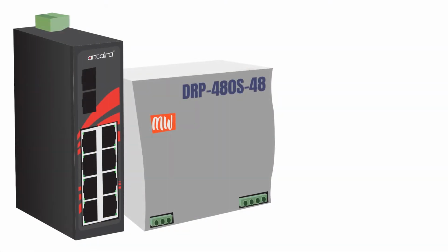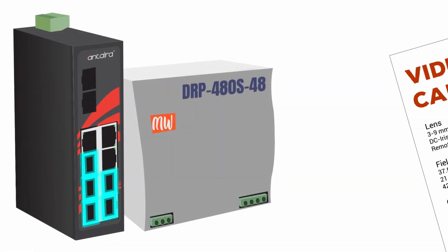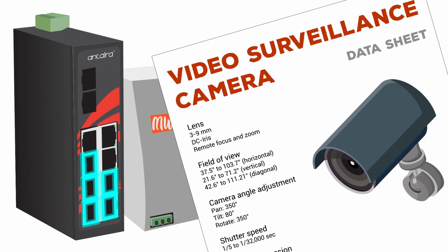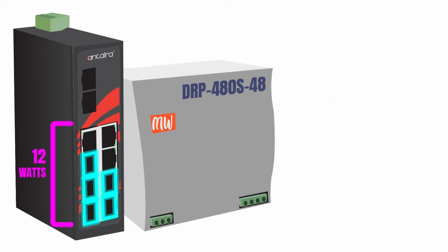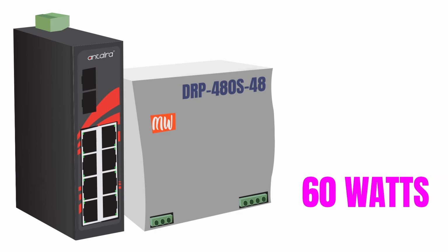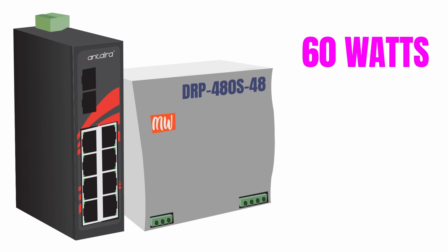Let's say that while the switch has 8 ports, you are only using 5 of them for PoE, and that you have looked at the spec sheets for the devices to be powered and have determined that they require about 12 watts each. Now you only need 60 watts for the PoE devices.